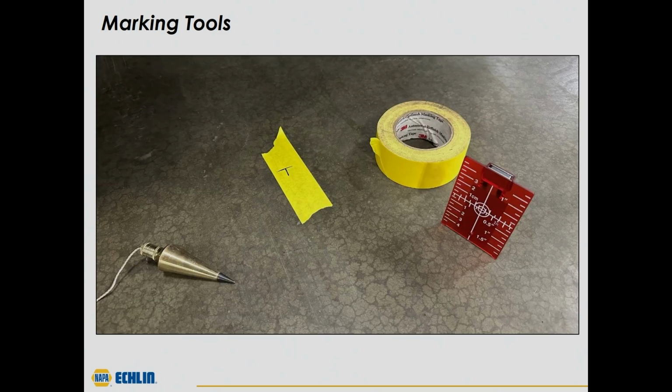Now, one thing I like to do if you're going to use the method of using a laser, I would get a reflector as well, and it's got a crosshairs on it in this example. And what we can do then is once we've actually dropped our center point to the front and rear of the vehicle, we can now use the reflector at the opposite end. We're going to have a laser at one side, a reflector at the other.